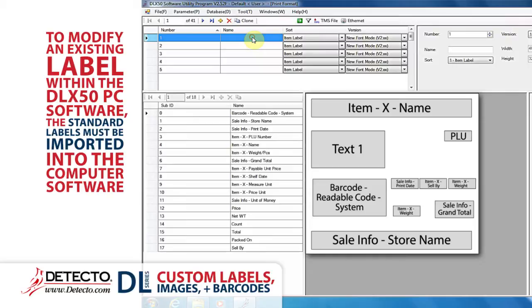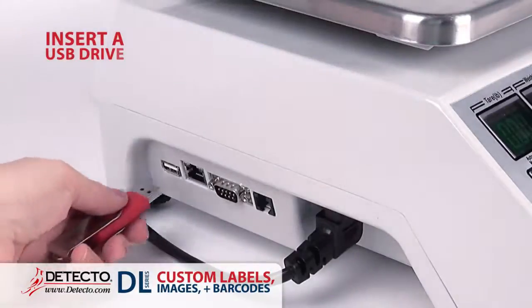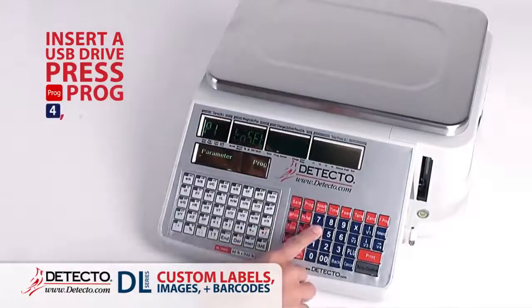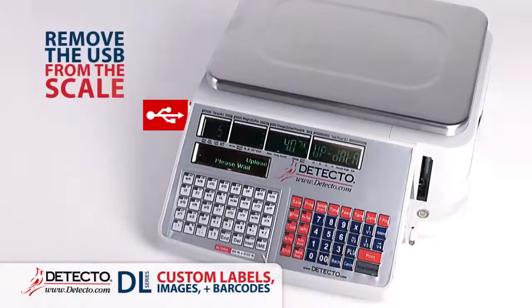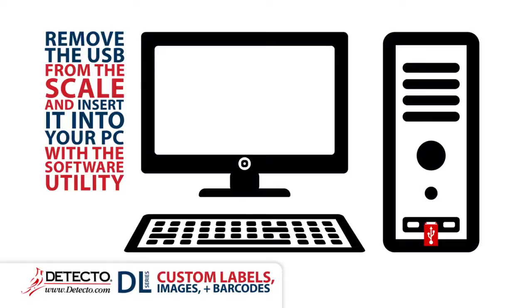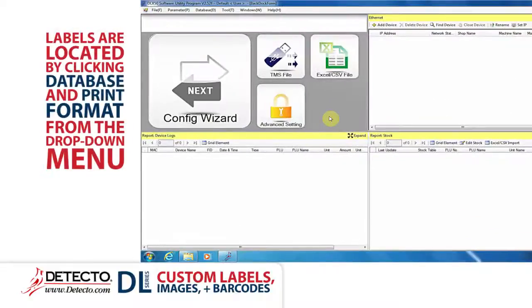To modify an existing label within the DLX50 PC software, the standard labels from the scale must be imported into the computer software. To do this, insert a USB drive into the scale, press Program 4, 1, and Amend from the scale's keypad. Remove the USB drive from the scale and insert it into a USB port on the PC that has the software utility installed. These labels are located by clicking Database and Print Format from the drop-down menu.